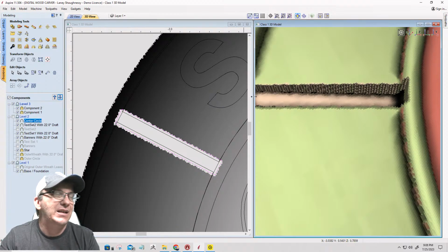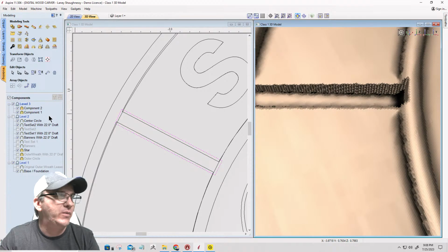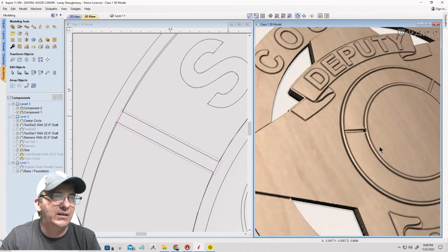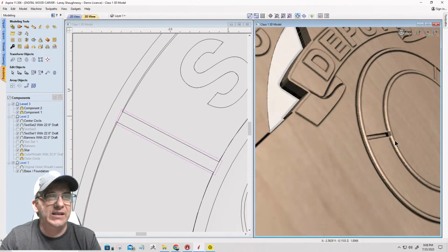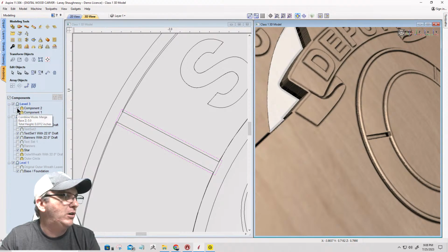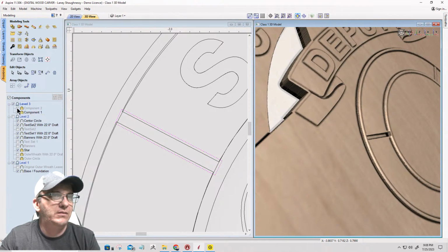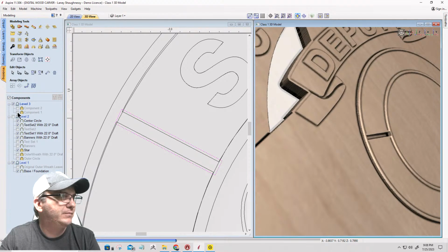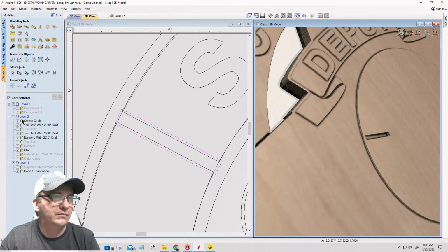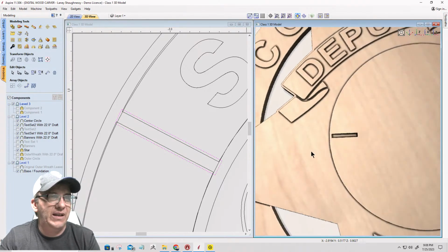And let's click off of this so we can see everything. It should have removed that center circle. Let's turn off the two berms. This one. And that one. Let's turn off those two edges for a second. Okay, so it's removed that material on that center circle.